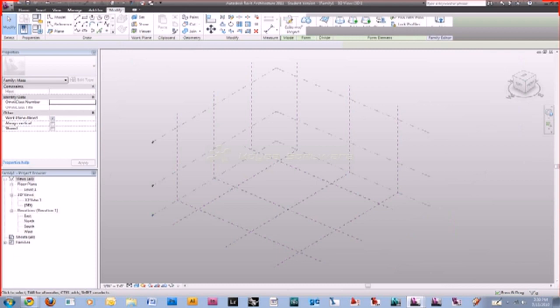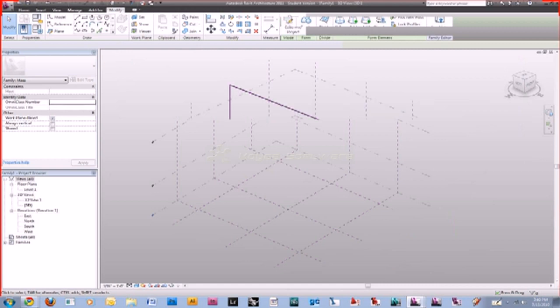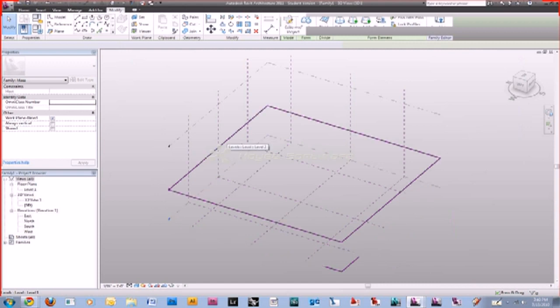So with revolve, we're getting a little bit more complicated here, so Jeremy's going to go ahead and start doing a revolve. With a revolve, you basically need a center axis and then half of a shape. It has to be a profile that can be wrapped around it. So you have to think three-dimensionally before you do this one. You've got to see how it would play out in your mind before you actually work it, and then take a slice of that, basically a section cut, but only draw one half of the section.